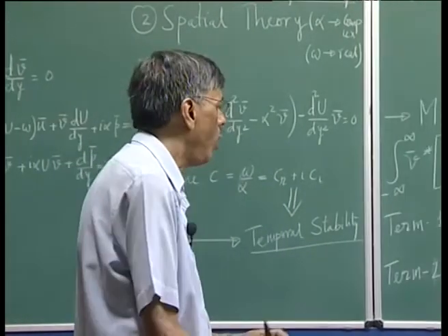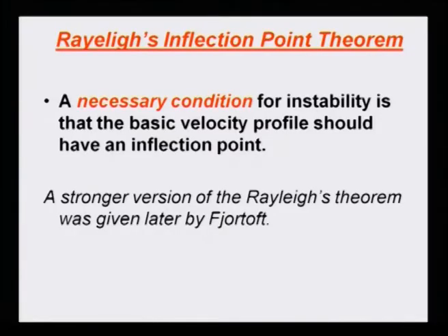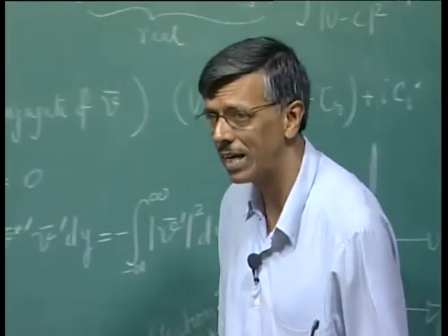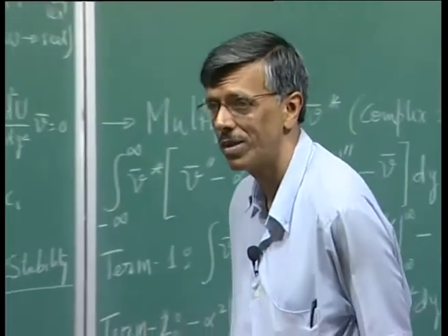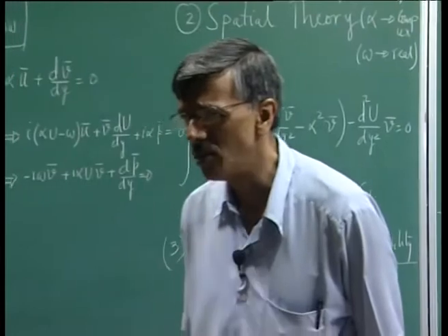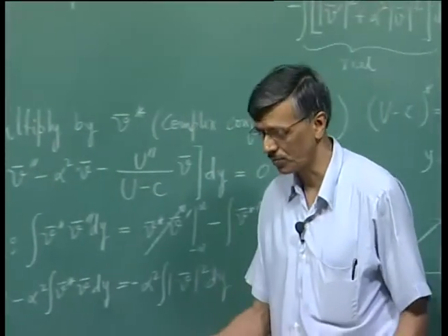right. So, this is what was done by Rayleigh, and as I told you, he did it without the equation. All he said was that if I can measure the velocity profile or I can get an analytic expression by looking at the velocity profile, the equilibrium condition itself, I can say whether that scenario depicts a stable or an unstable condition. Okay.